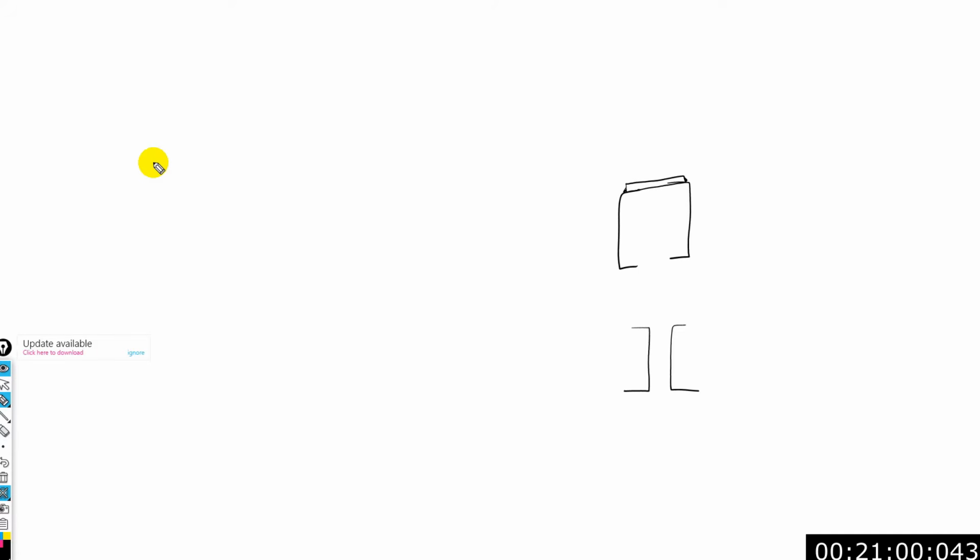So generally for the residential building, the section for beam may be used as ISMB 200, 250, 150 depending upon the condition, but it is not provided greater than 250. Generally we may go up to 300 as well. So for now, considering 250 as the maximum size, that means the beam is going to rest and be connected on this point, on this face. And if we see in the plan, so this will be the flange of the I beam that will come, and this is the web.